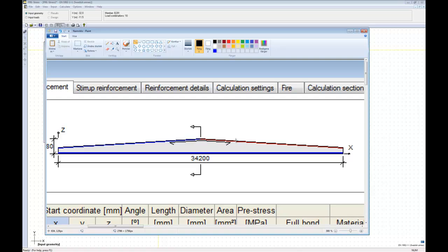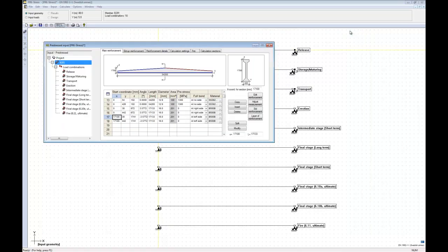So we will anchor the right bar with this kind of reinforcement bar. And that reinforcement bar you have to add when you're making the drawing. It will not be considered in this calculation here, because it's only for anchoring of the bars here. And we basically say that it is fully anchored in the right side and the left side.